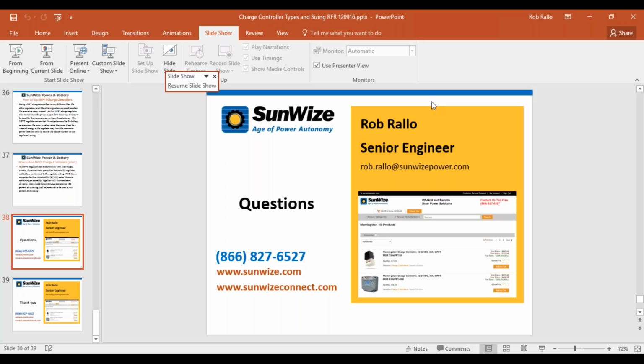There are a couple of brands that are. The ones I'm mostly aware of are either the shunt regulator, the ASC that I mentioned earlier, which is certified for that, and I know that the Morningstar SunSaver, the pulse modulated unit, is also certified for Class 1 Div 2. And again, that's because they're solid state, and you also notice they're smaller units, again because of the heat dissipation.